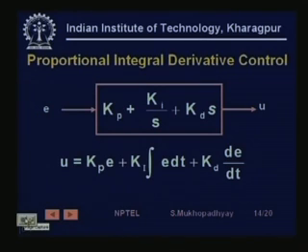One thing interesting to see is that we now calculate the input like this. Interestingly, in the steady state, the total E is 0, so this term is 0, so the proportional part is 0, and since E is not changing, d/dt of E is also 0, so that is also gone. So, we only have the whole output coming from the integral part. So, the 0 steady state error concept that we have studied for the integral control holds.